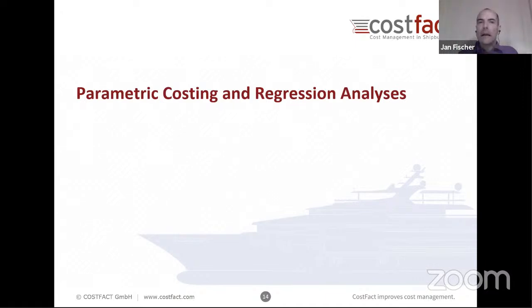All right. CostFact does not come with numbers about how time-consuming it is to make a weld or something like this. CostFact is only a shell for the data from the shipyard. The shipyard uploads its own data about unit rates or norms. All shipyards have their norm tables, where it says, for us one meter of welding takes 35 minutes, and another shipyard has another system and it takes 25 minutes. This specific data can be uploaded into CostFact, and then each shipyard works with its own data.